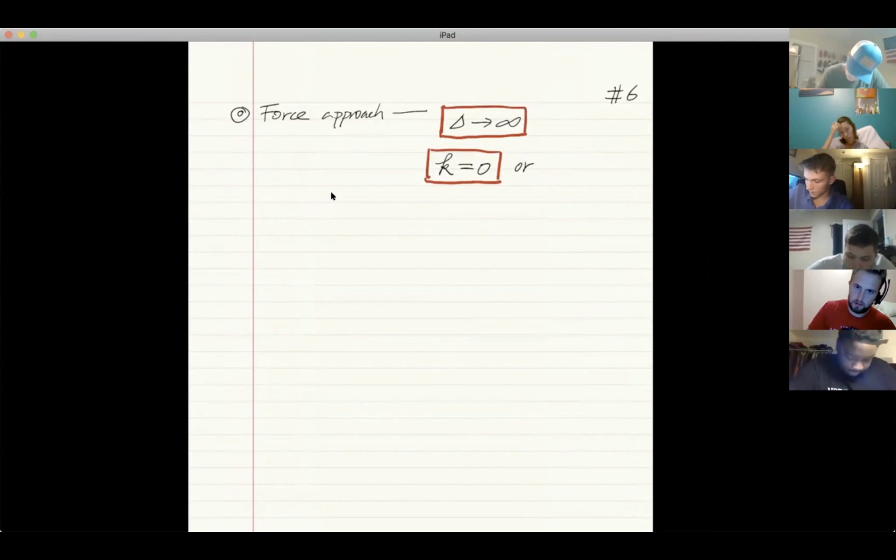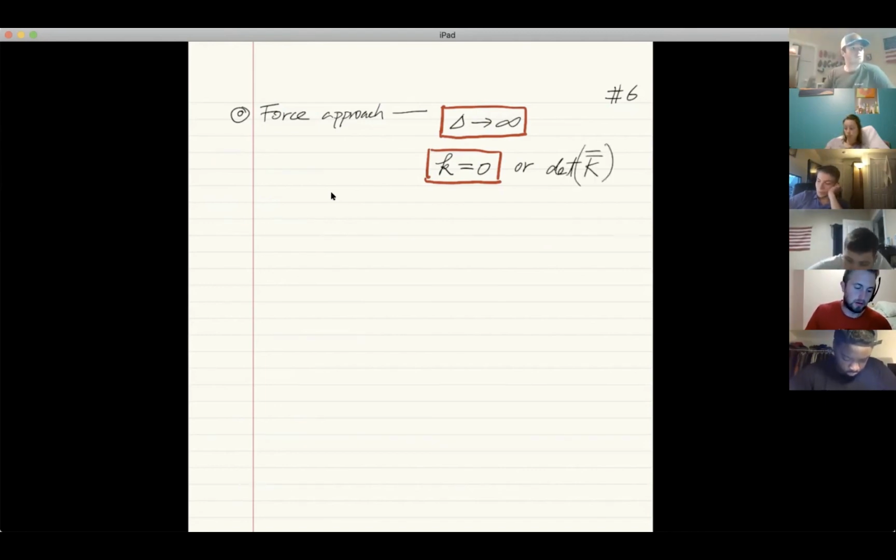In that case, you don't have just a stiffness coefficient, you have a stiffness matrix, defined by capital K, since I have 2 bars, that means it's a matrix. When the determinant of the stiffness matrix becomes 0, that's the case we call buckling.